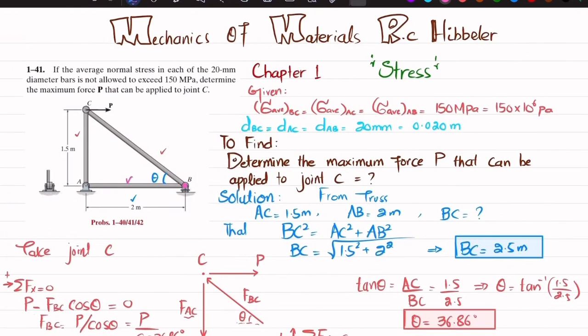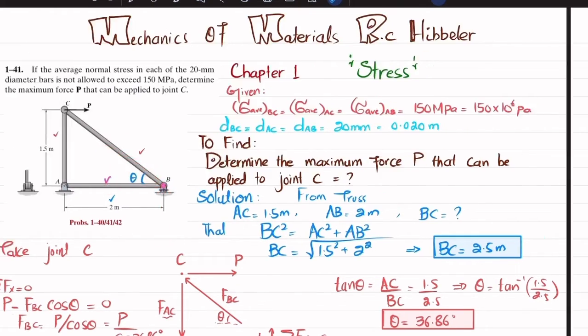Okay, so here at point B you can see that you have a reaction force due to this roller support at point B. This is By. Due to this member BC, there is a force in this direction, FBC, and this makes angle theta with horizontal, and there is a load due to this member FAB. So the load will be like this one. So we will draw it over here.